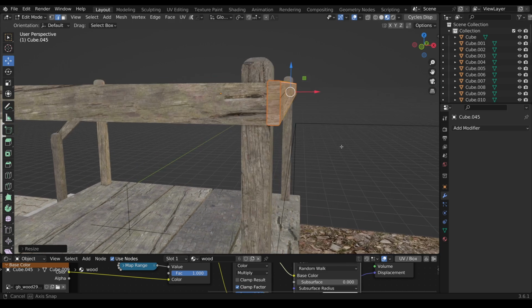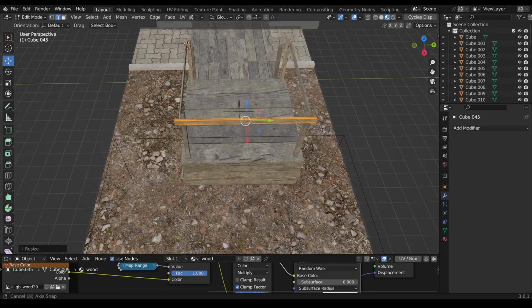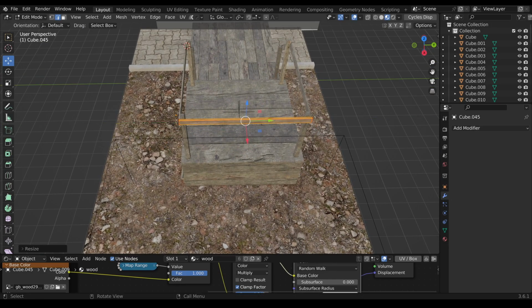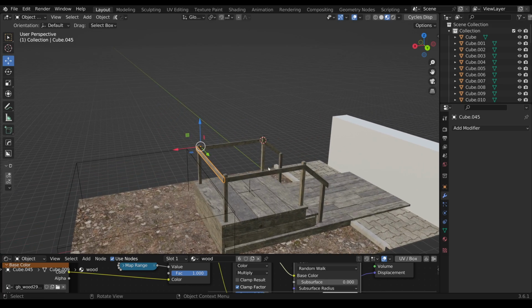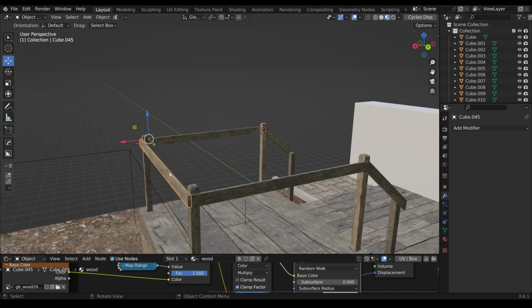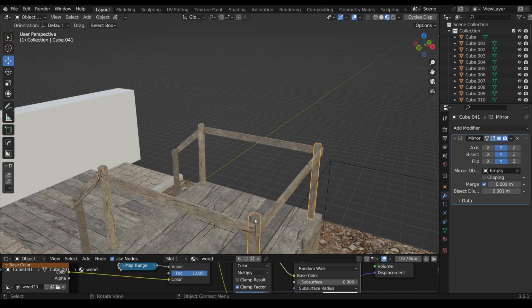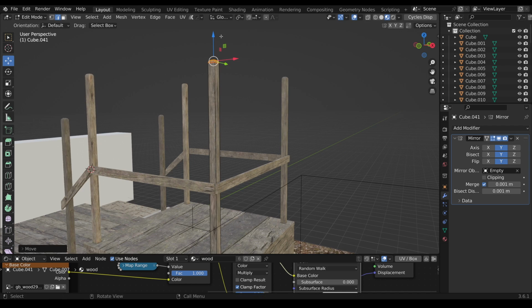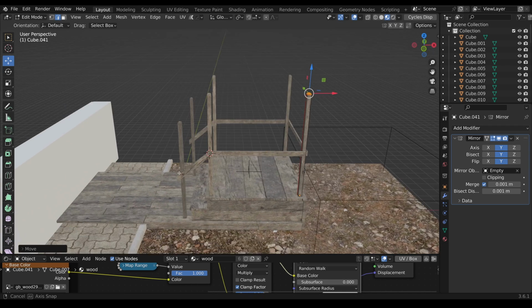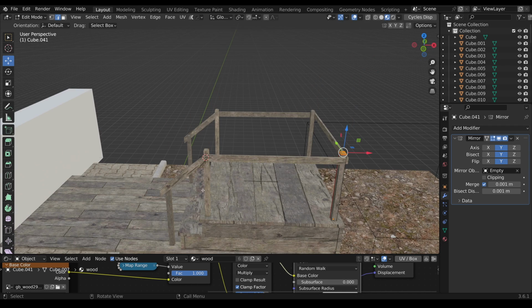Adjust it a bit on Z. Perfect, and it's done. I had a roof on my sun terrace. Let's take a look at that. The good thing is, since we're using mirror modifiers and these two have the same geometry, it's enough to edit one and extend it upwards accordingly. Oops. This was also copied with Alt+D.